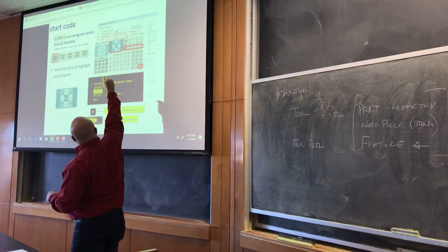And if you happen to have a piece of fixturing that's in the way, the tool rotating around in the tool carousel will hit that piece of fixturing, but it's still attached to the tool carousel. And it will break the tool carousel. So try to avoid that. There's one of those mounted on the wall in there.